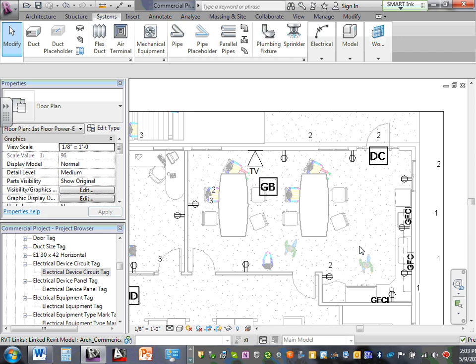We call this a tag. Oh, unnamed? Okay. Now when it says unnamed, this means it's not circuited properly. If it's unnamed, it's not circuited. So that's easy. Click on that one. Let's check. Did you pick a panel? See, we forgot to pick a panel here. Pick the panel for it. There you go. Now they're all circuited.